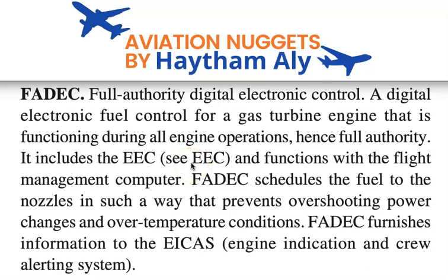From the ADRU, air data computer, to the FADEC there is a direct communication, and there is also non-essential communication, or other aircraft systems that must be connected to the FADEC or the EEC. This may be done by another computer which may be called an interface concentrator.